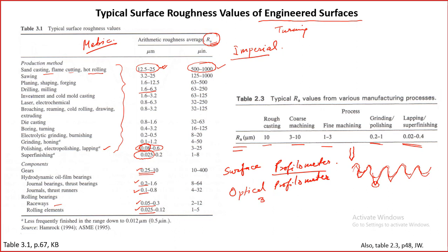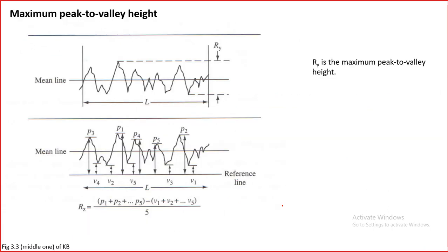It's also sometimes known as a 3D optical profilometer. Here, light is used, and using some interferometry, the roughness or the profile can be obtained through the optical method. This is quite popular nowadays, because it gives data for a full area quite easily. For example, this area I want to scan for roughness, so I can measure the roughness in all of this, and then using some software we can plot and see how the surface looks.